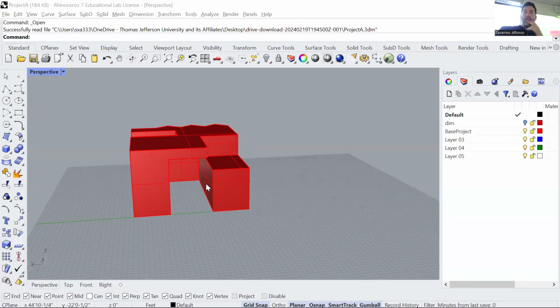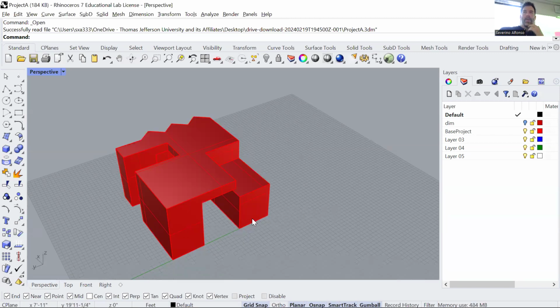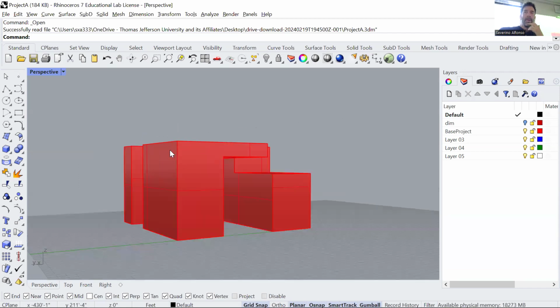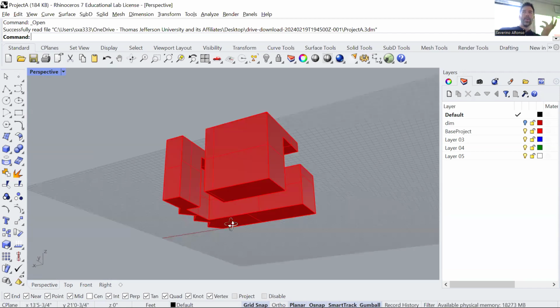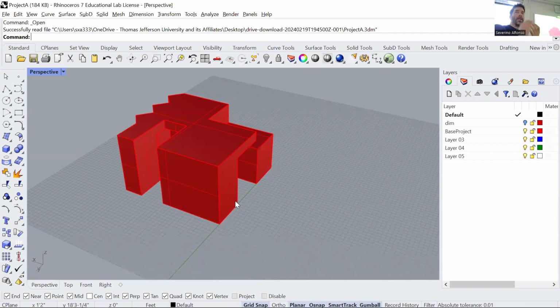After it opens, this is a project that probably makes more sense to laser cut because of its planar condition. You can also 3D print it, but you have to slowly start understanding what proposals make more sense to laser cut and which ones to 3D print. In general, if there are a lot of planar surfaces, like in this one, probably laser cutting is going to be better.